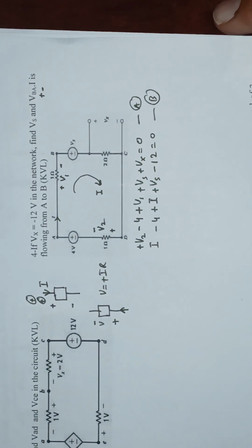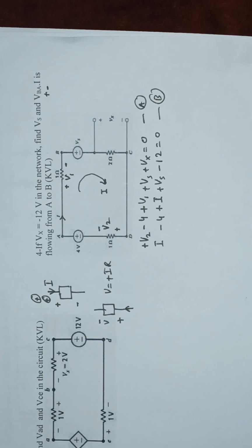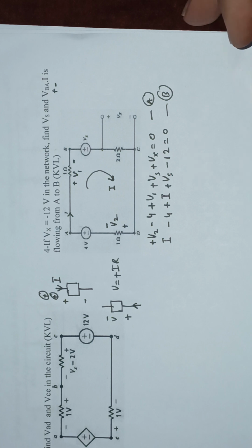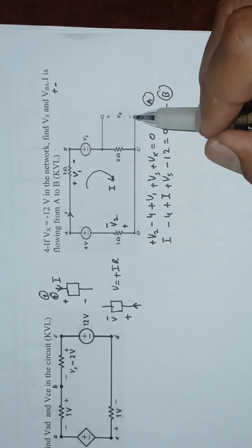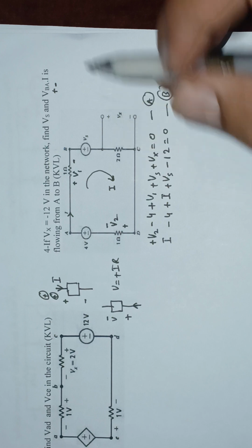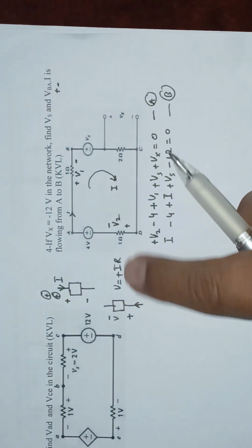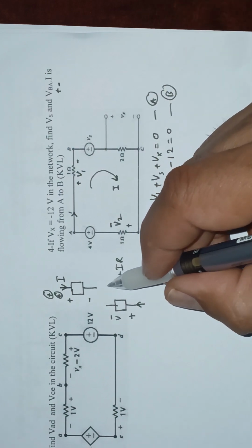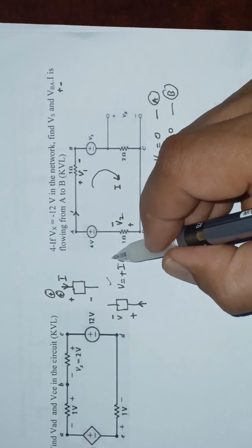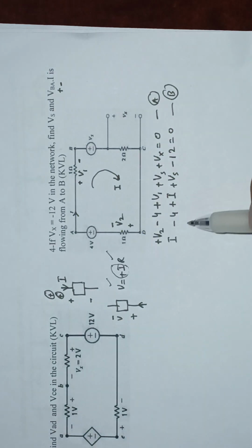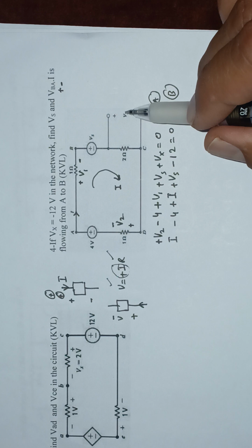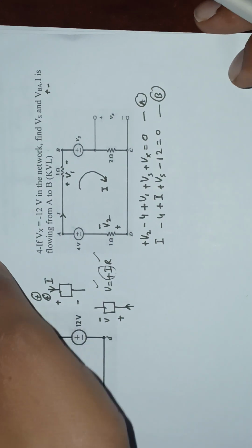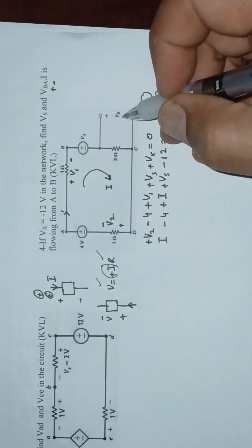Now, because this is two unknowns and one equation, I have to rely on some other strategy. Since I know this voltage and this is the resistance, then with Ohm's law, if I have one equation and one unknown, I can find it. Vx is given to us, a resistance is given to us, so the unknown is current. So I can find that current from this given data and then insert the current here. Then this is one equation and one unknown. So I'll apply Ohm's law here.